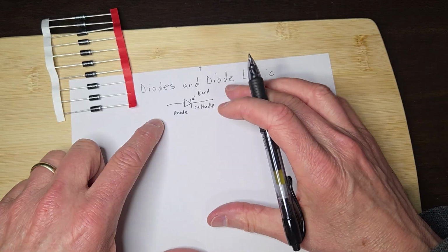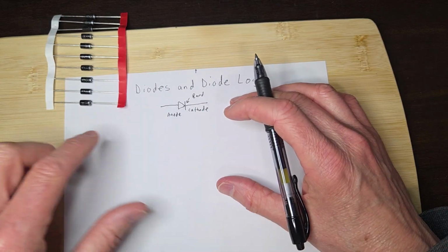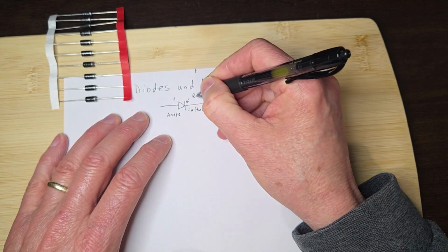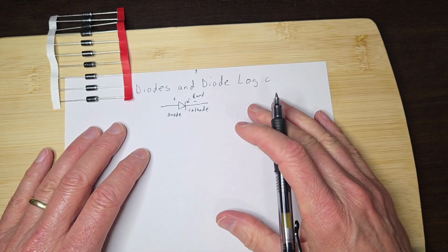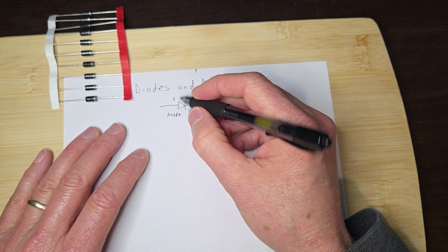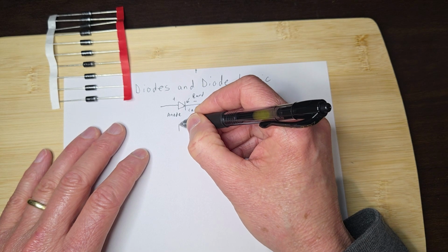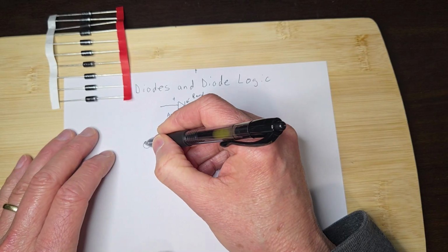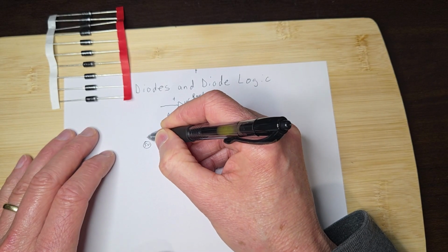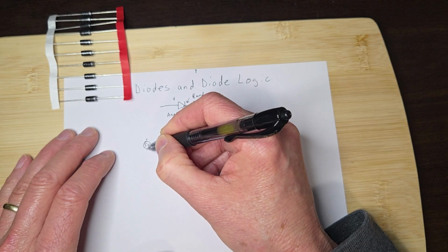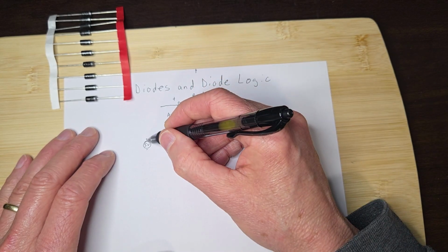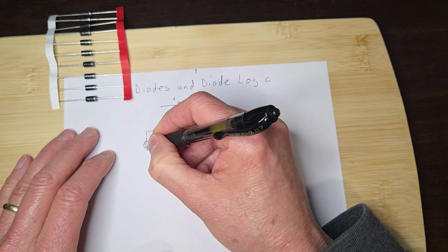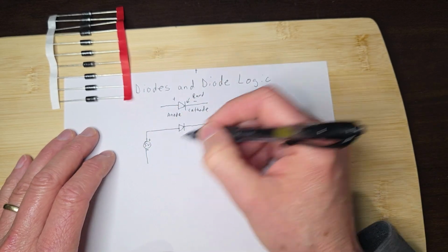And these are important: unlike resistors, where we don't worry about biasing and you can put them in either direction, diodes are biased, so this would be positive and negative right there. The way it works is you would have a diode in a circuit like this. And let's say you just have 5 volts, plus and minus. Actually, I should have put the 5 volts out here, but you get it.